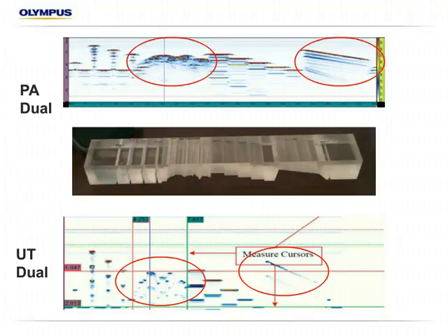So the PA dual, the DLA that I was just talking about, we basically take it out, select the file of the right thickness, change the material velocity to represent the block here, and move the gates a little bit, and with scanning we get very even, very good quality data of all the types of reflectors that we're looking for.